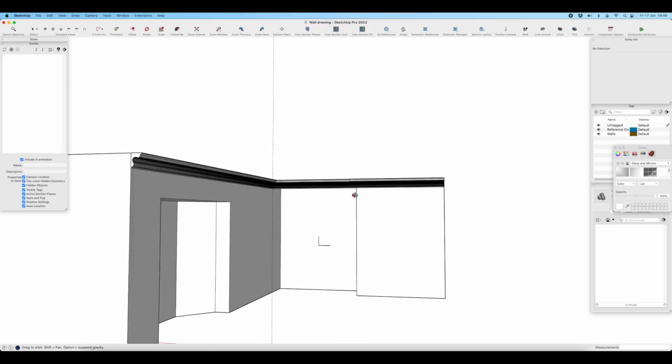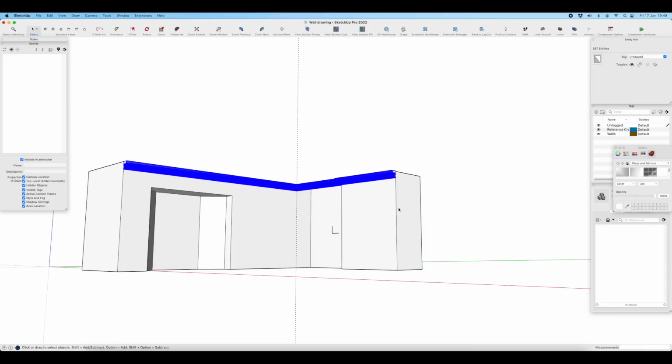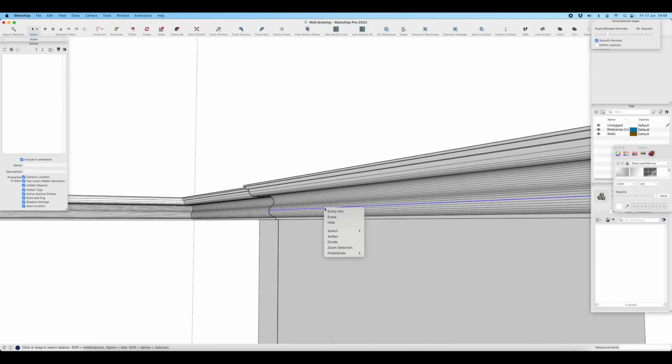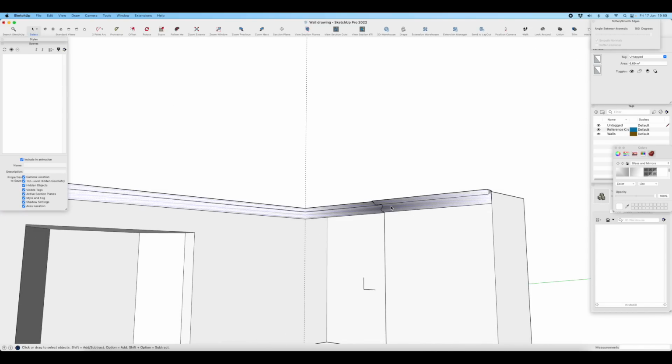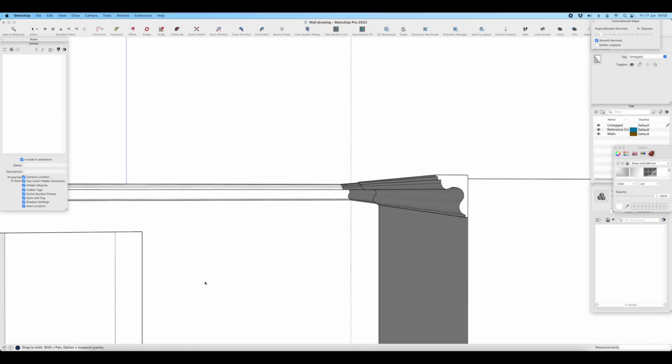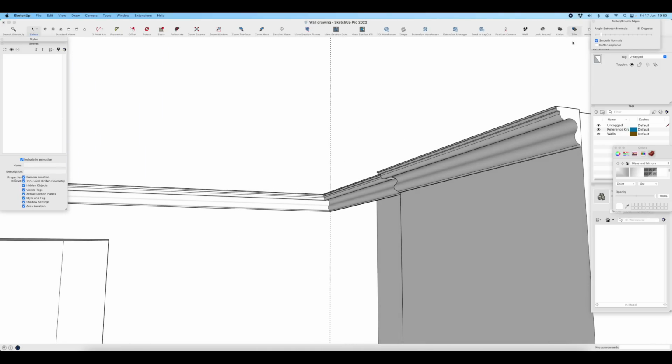And we've got ourselves a bit of coving. We can select all that and soften the edges to try and get rid of some of these lines. On the Mac we've got a soften smooth section up here, so we can adjust how much of them lines we actually want to see. I'm just going to do it until we get rid of them dark heavy lines, but we can still see the detail of that coving on this soften smooth edges section at the top.